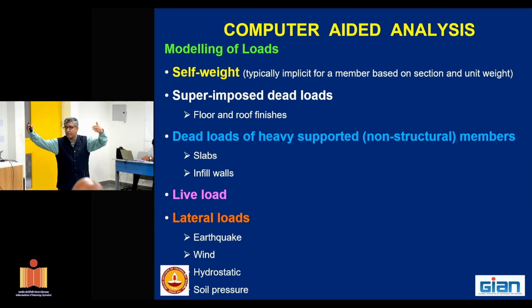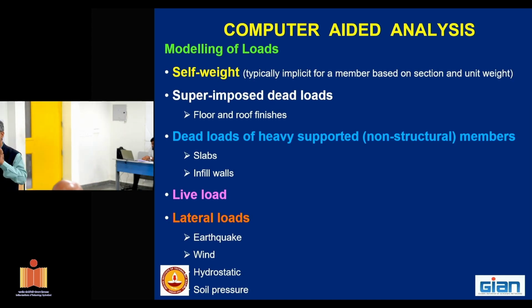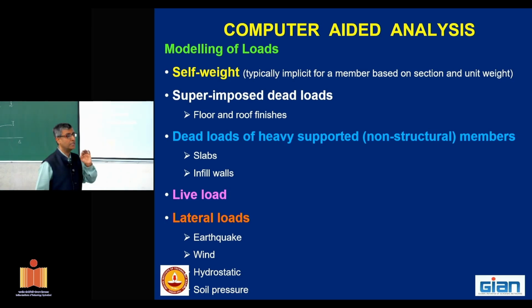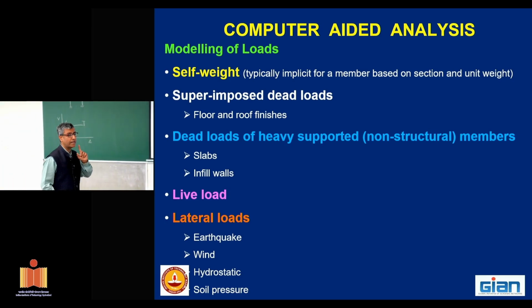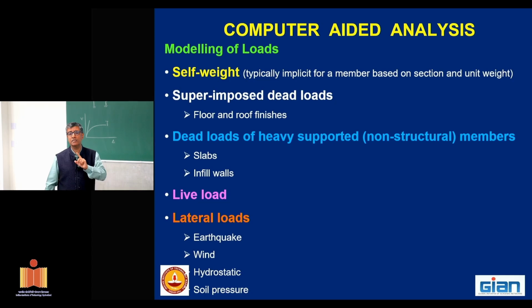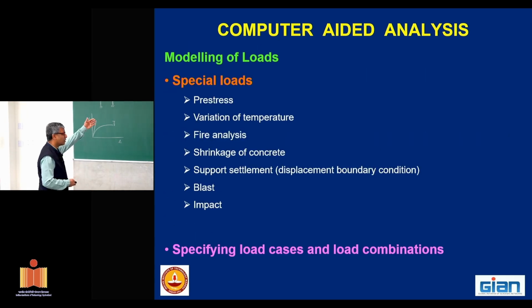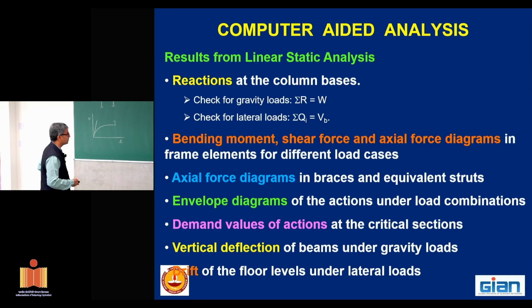If I am having heavy brick walls, I need to incorporate that. Hence, that's your responsibility, that you have to include all the heavy loads. And as I said, earthquake especially is very much weight driven. Then appropriate live loads and the lateral loads. There you can also do an analysis for special loads.